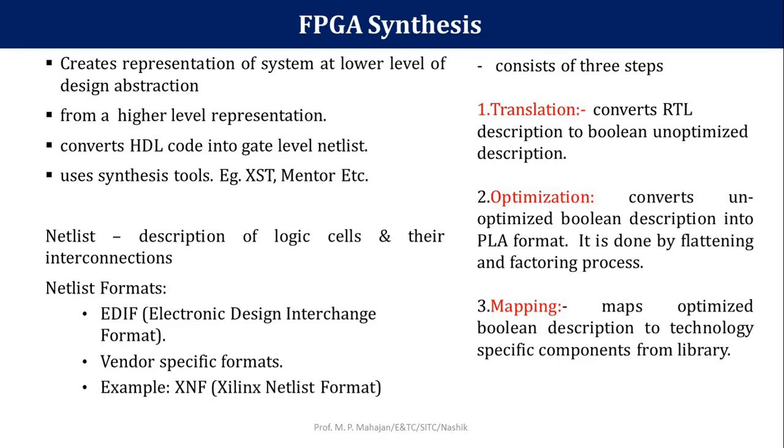This process converts your HDL code into the gate level netlist. Hence, we can use different synthesis tools. For FPGA synthesis, we can use most probably the Xilinx synthesis tool and Mentor Graphics tools. These are very popular tools. Nowadays, Altera Quartus is also popular.